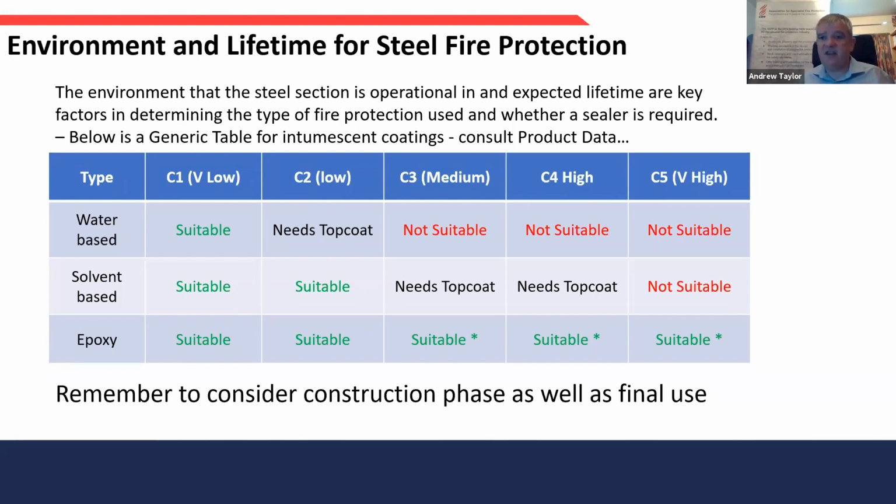But if that steel frame is going to sit open to the elements as a construction site for 6 months, 12 months, while the office is being built around it, that is a much more onerous environment than the rest of the building's lifetime. So please consider construction phase as well as final use, because it's an area we see things that may be causing issues going forwards.